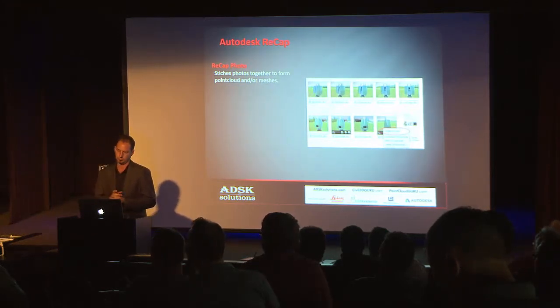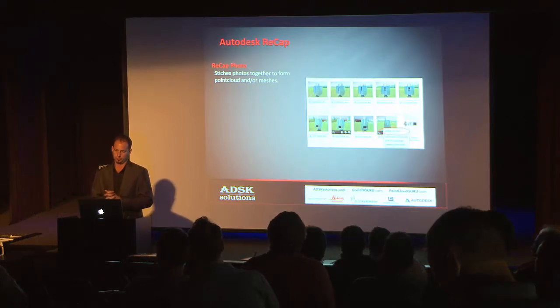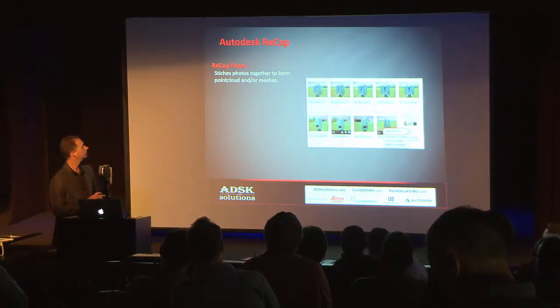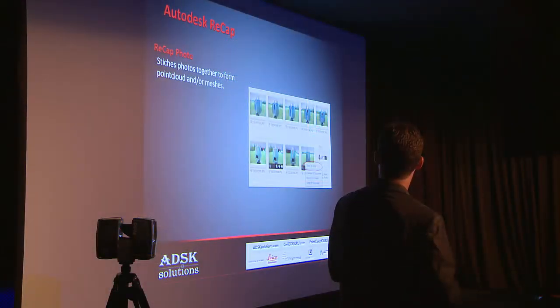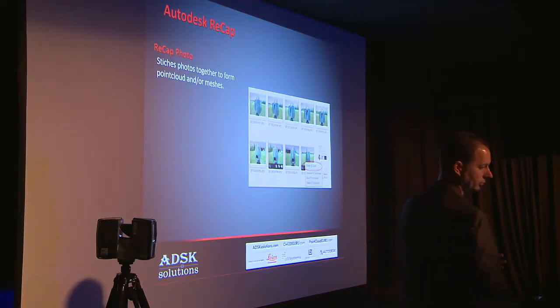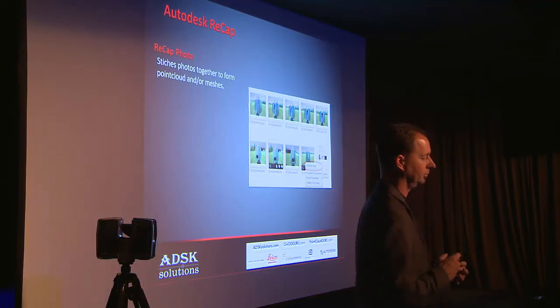But a few things just from this image. You notice that he's got both the object and the background. The background actually matters, even though it's not a part of the 3D model. We're using features both of the object and surrounding it to compute that 3D geometry, so it's good to have the background. He's done a good job in this one. About 50% of your image should be the object you're trying to capture, and the other 50% should be that background. You can see here, he's probably got that mixture in there.